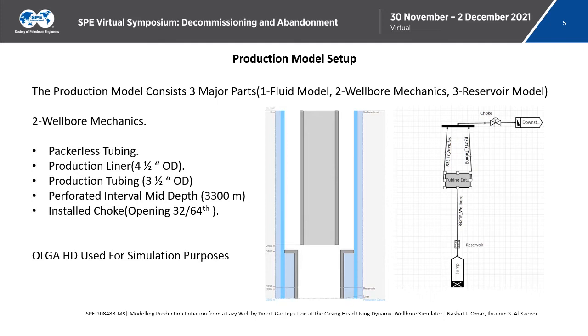The mid depth of the perforated interval is 3,300 meters. Additionally, there is a choke installed on the wellhead, which is normally opened at 32/64th of an inch. Again, the OLGA HD model is used to simulate the flow from the well.